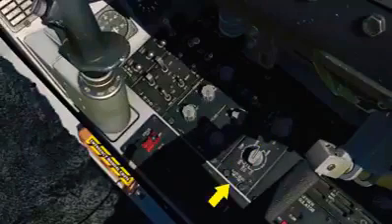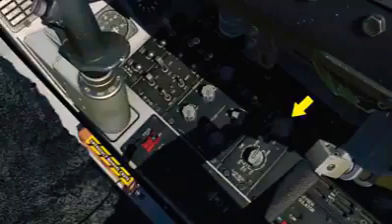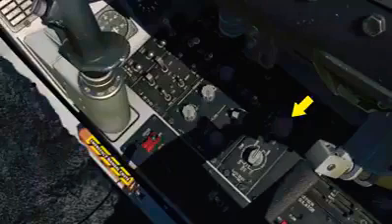The environmental control system panel is split between setting the cockpit temperature and setting the bleed air source. The temperature control has really no function in the simulation, but the air source knob has options to close the bleed air valves. Normal sets the ECS for automatic operations. Dump equalizes the air pressure to the outside air pressure, and RAM closes the bleed air valves and dumps the